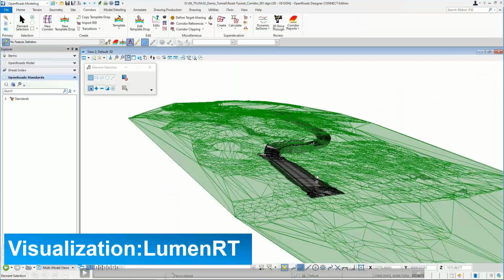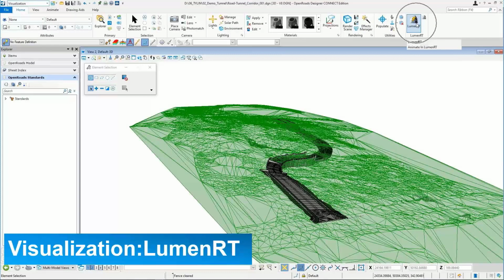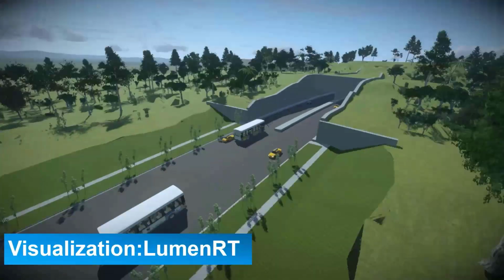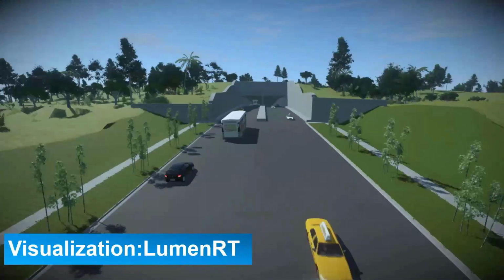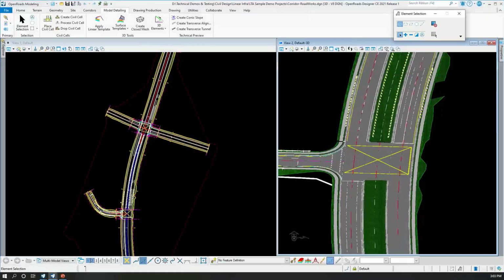Then if there's a need for you to create a nice visualization of your project, you can output your design to LumenRT, which comes for free in the software, so that you can create a sample visualization like this. All you need to do is just finish the model, export it by clicking that particular button, and you would now be in the interface of LumenRT, and then you can just add in some of your trees, cars, and other animation that you need.